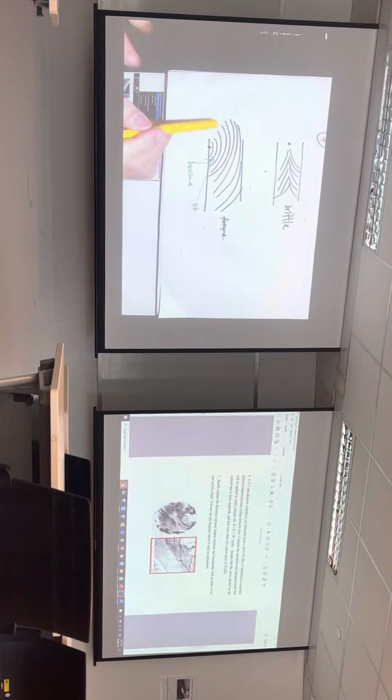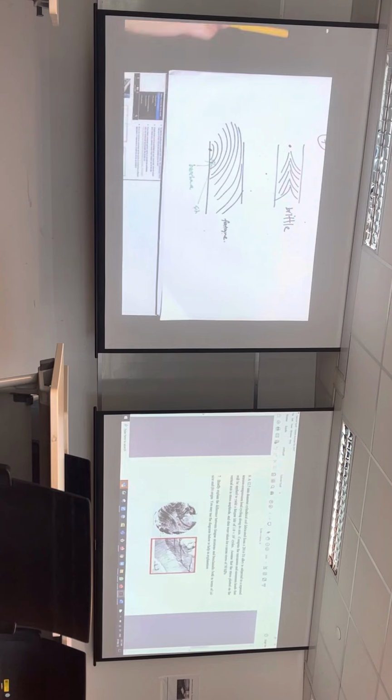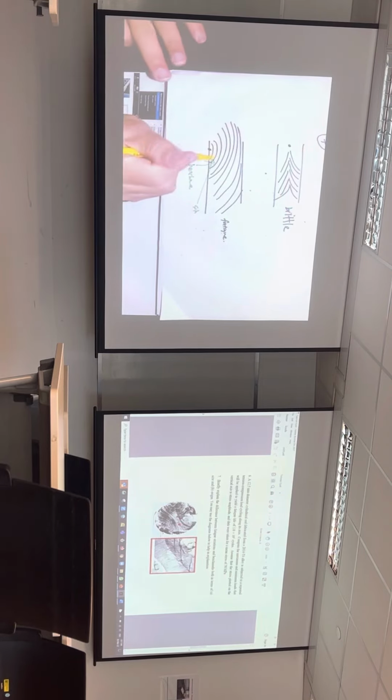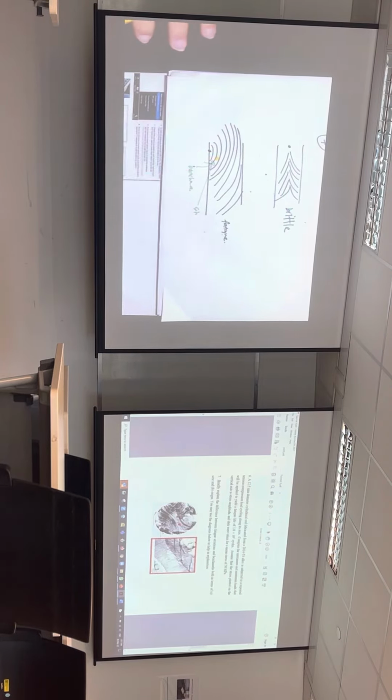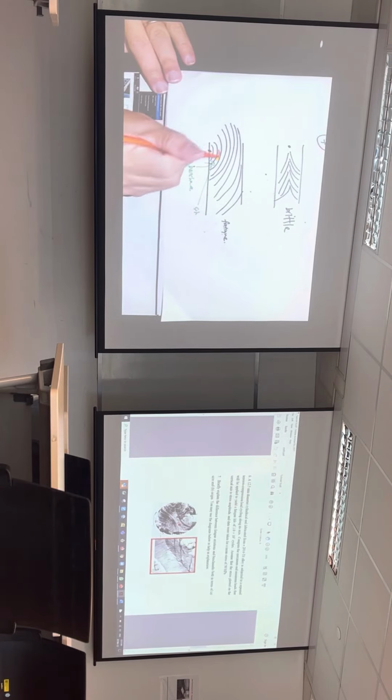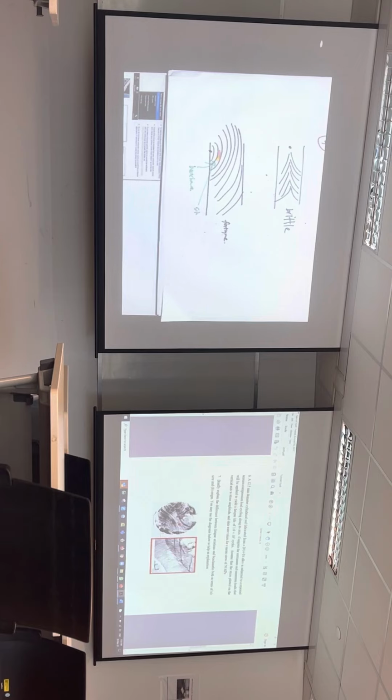The beach marks are all these big lines, macroscopically visible. Striations you have to look at with a finer scope, but you still see the same kind of lines, going in this way. They are very fine, and they are due to the loading of a smaller load cycle. How do you spell striation? It's in the question. Striation.